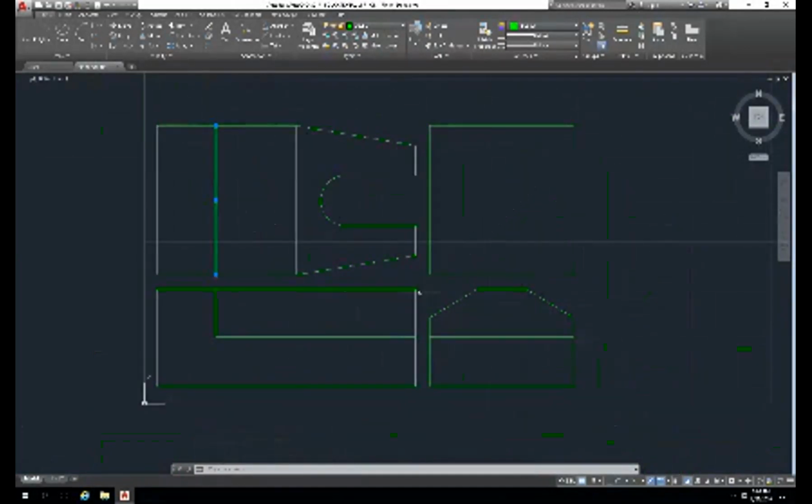So now I have to escape line. Now I have to, let's do intersection. And let's turn on ortho with F8. F8. And then line, intersection. See the cross? That means an intersection. Okay, enter. Line, intersection. And obviously you can turn on intersection in OSNAP, but when you're dealing with lines, you end up with endpoints being in the same places as intersections. And so when you're moving the mouse, it kind of sort of flickers,